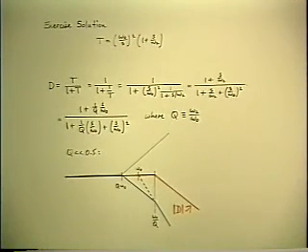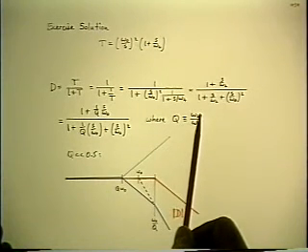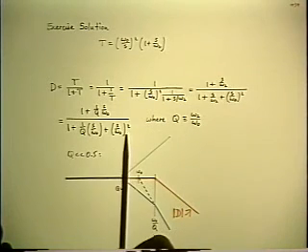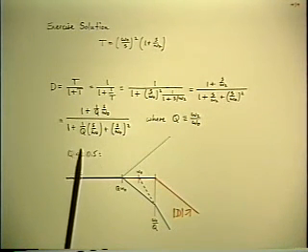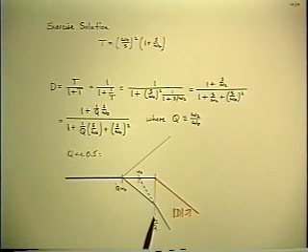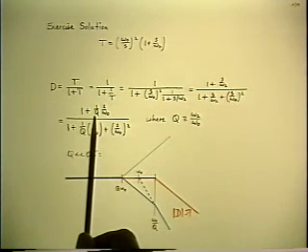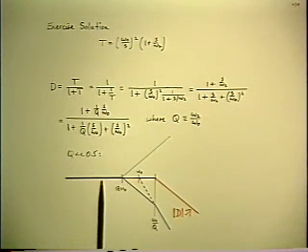So you sketch the typical case for each of the ranges. What happens if Q is very small, which means that the compensating zero is well below the original crossover? That means you can factor the quadratic into the two separate real roots, and I've shown it done graphically down here. That means that the two real roots are going to be Q omega 0 and omega 0 over Q. That's the blue asymptotes, the two real roots. But there's also another factor in the numerator, which is a 0, and the position of the 0 is Q omega 0, and that's the green asymptote.